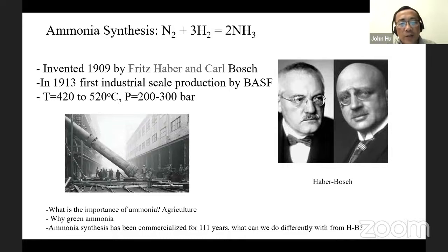I think 1 inch is 2.54 centimeters. This reactor wall is 8 inches, so 8 times 2.54. That's a high-pressure reactor. In the old days, they could not machine the reactor very long. You see that in the middle, they still have a flange. Today, you don't machine it that way. You basically weld it. You don't want to use a flange.